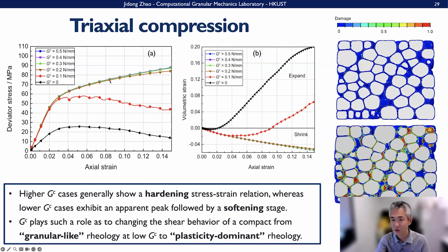Okay, and this is quite similar to some kinds of sand. Loose sand and dense sand have relatively different behavior here. For example, here the volumetric strain evolves with axial strain changes. This non-cohesive case gives us a quite typical contraction and then dilation curve. It's quite like a dense sample, and we will first have a contraction, then dilation here.